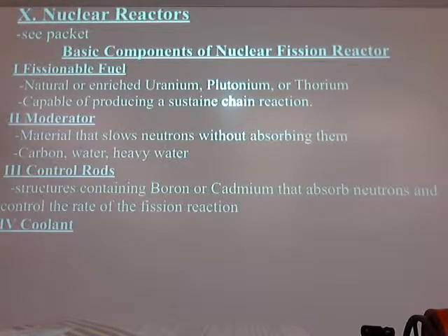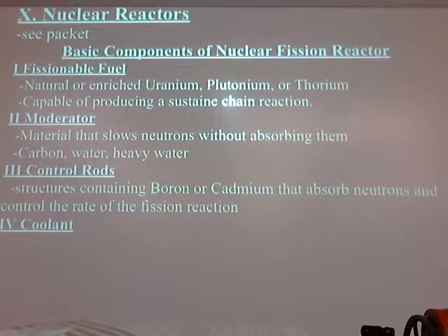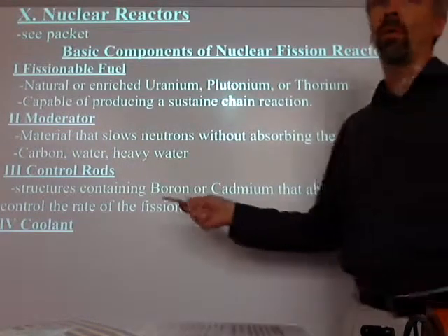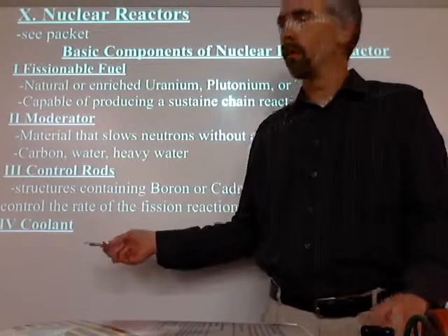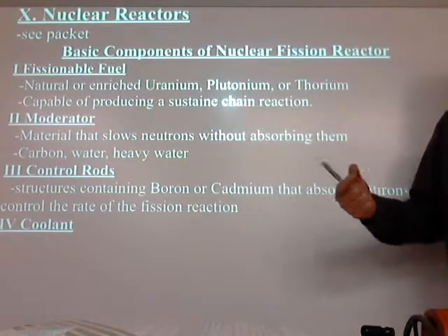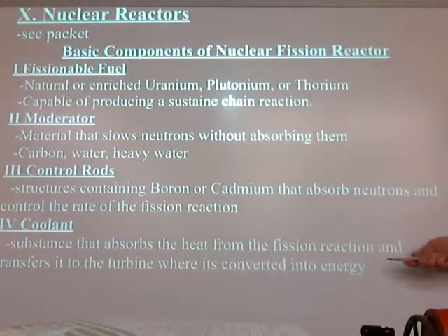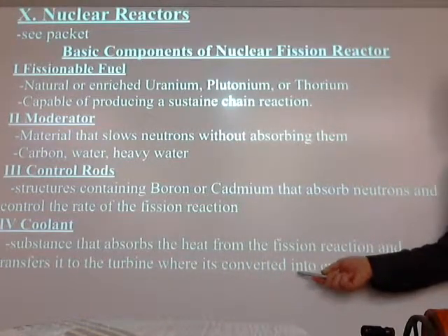You also need a coolant. You're generating a great deal of heat here, people. You better have some way to dissipate that heat. And this coolant actually serves usually two purposes. One, to cool down that core. If it gets too hot, it's going to melt. If it gets too hot, it's going to get out of control. Okay? But the other reason is we need to boil water.